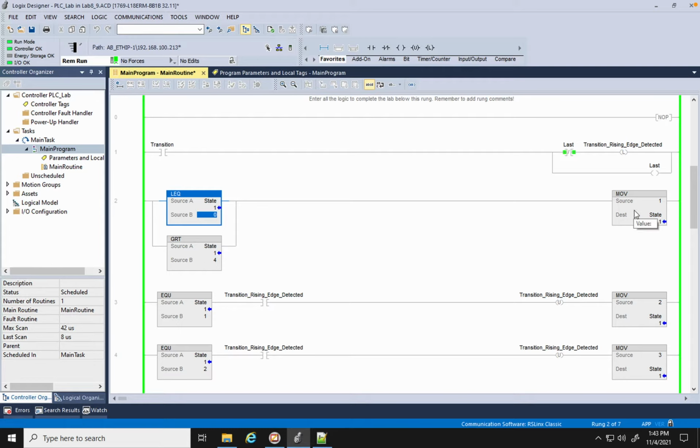Well, it's going to default immediately back to state 1 because 100 is outside of the bounds that I've set. I've said if our current state is less than or equal to 0 or greater than 4, then move directly to state 1. So this allows us to have a default state as we should with any state machine.